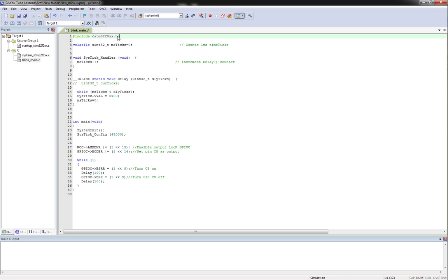The thing we want to make sure we include, kind of like how we include 16F676.h, is STM32F0xx.h, which takes care of the F0 family, the whole family of stuff. So you want to include that header file. That's definitely one that you want to do.